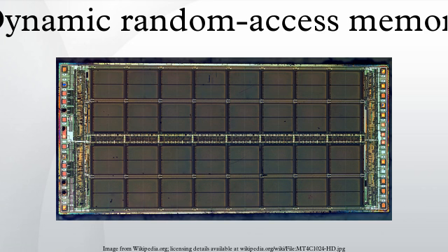There are several types of 1T DRAMs: the commercialized Z-RAM from Innovative Silicon, the TTRAM from Renesas, and the A-RAM from the UGR/CNRS consortium. The classic 1 transistor 1 capacitor DRAM cell is also sometimes referred to as 1T DRAM, particularly in comparison to 3T and 4T DRAM, which it replaced in the 1970s.